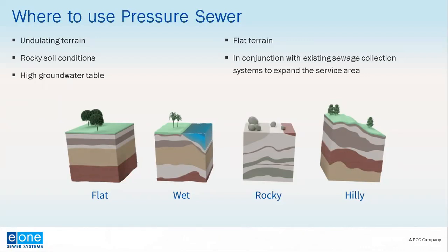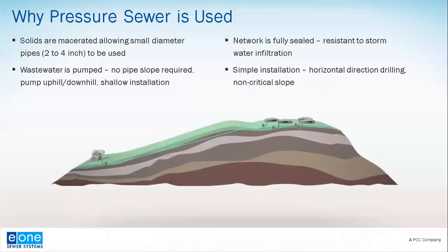We know from speaking with stakeholders and end users that dewatering costs and regulations are higher and more stringent than they ever have been. Pressure sewer, because it's minimally invasive, can help eliminate those costs by eliminating or reducing open trench techniques, where the terrain is flat, and also in conjunction with existing sewage collection systems to expand sometimes existing service areas. And why is pressure sewer used?